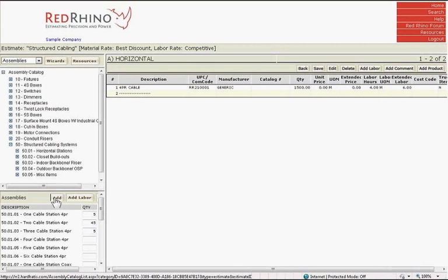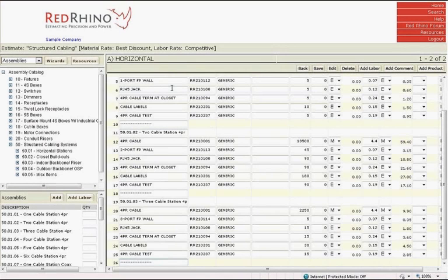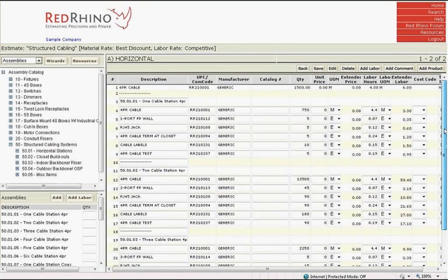Right here it gives you all the components. You have the 4-pair cable, the cable faceplates, jacks, the terminations, and cable labels. It's all right here. Notice that the closet side termination racks are not included here. Whether it's on a wall field or in a rack, whether it's a 24-port or 48-port patch panel, closet side terminations will be included in the closet section.